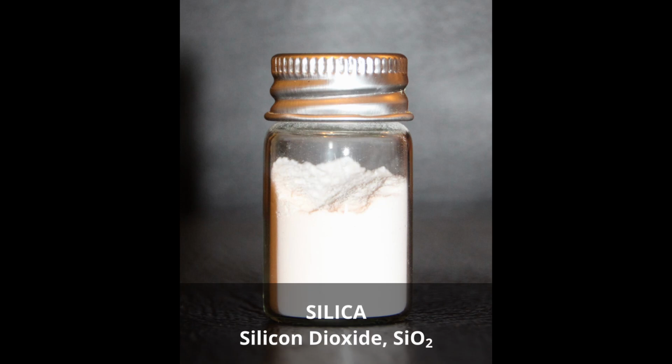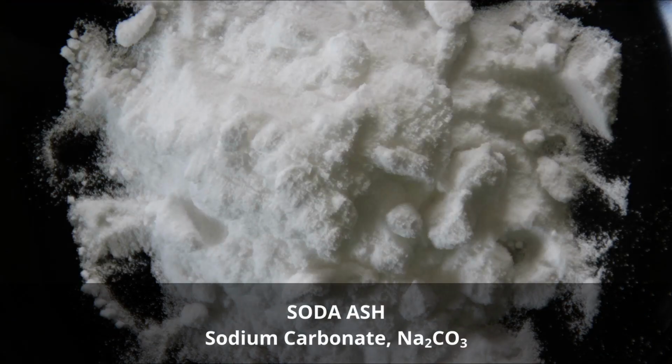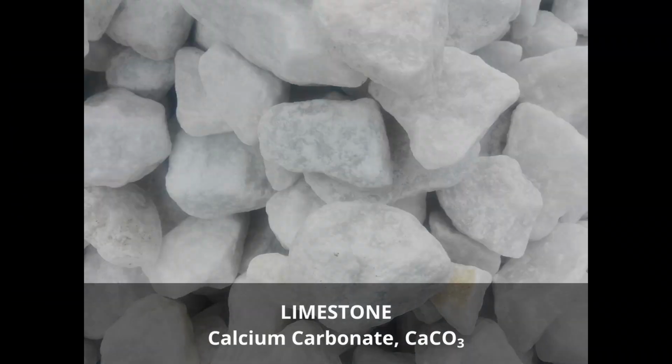The primary raw material for glass production is silica, or silicon dioxide. And while it's possible to make glass out of 100% silica, it has a very high melting point of 2000 degrees Celsius, so soda ash is added to lower this down to 1000 degrees Celsius. But doing so makes the glass slightly water soluble, so limestone is added as well as a stabilizer. It increases hardness and chemical durability and makes it so the final glass product is insoluble.